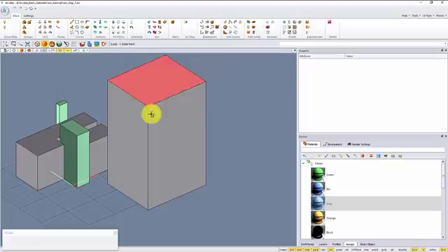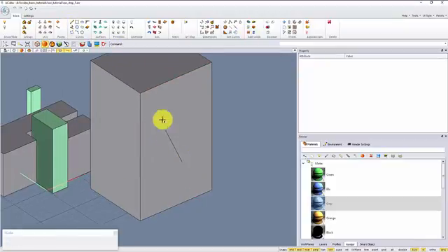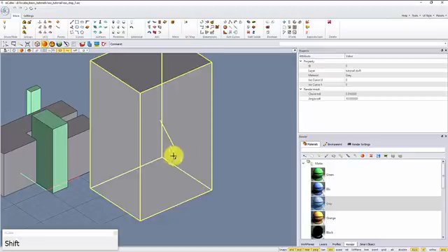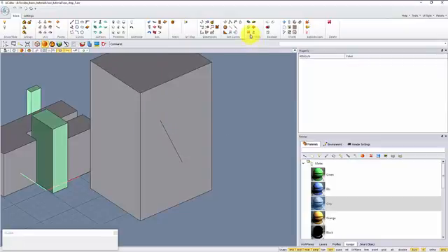Another useful tool is the edge remove. If we draw a curve like this, the curve is inside the surface. If I shift click, you see I am not able to select the curve, it is part of the solid. So the edge remove will delete internal edges.